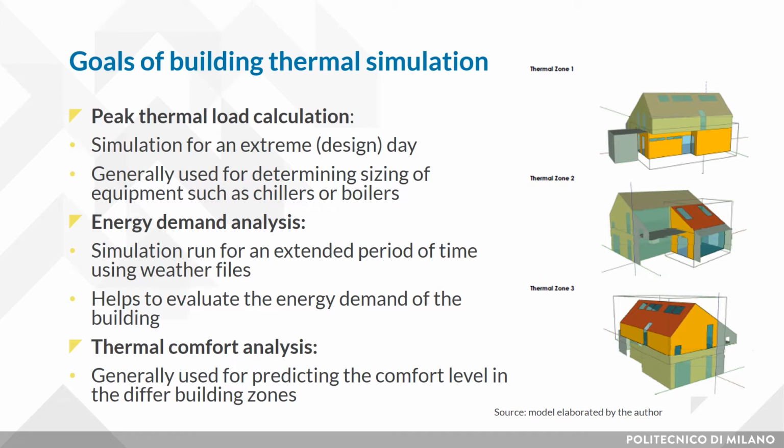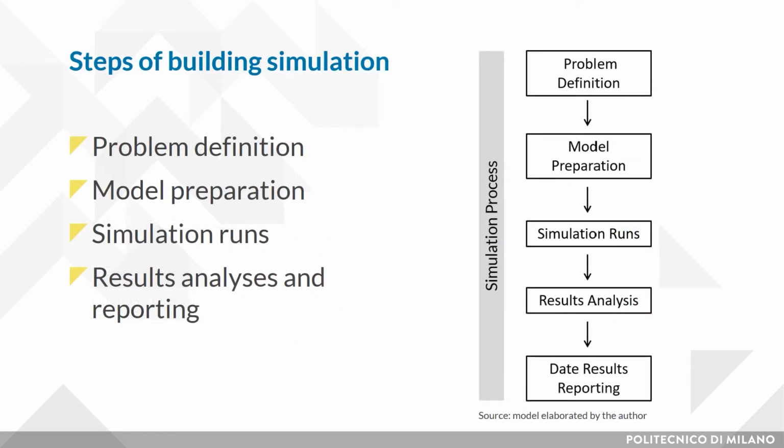Simulations are also used to predict the user comfort sensation in terms of predicted percentage of dissatisfied in the different building zones. In all the cases, the output data representation is very important in order to understand, share, and comment on the results, and if necessary, persuade the client. The simulation process is generally composed of four main stages: problem identification and definition, conceptual model development, simulation runs, results analysis and data reporting. Report generation and data visualization is a critical link in the communication process between the modeler, the designer, and the client.